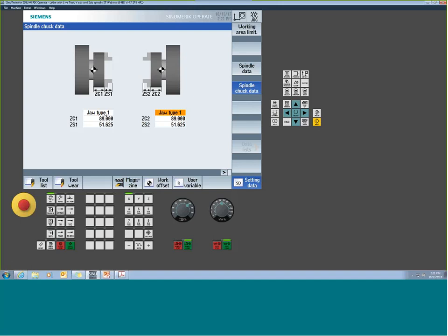Now, if it's a case where it's like a collet and the body to the base collet position is the same value, you don't have to have a number in here for the jaw projection. You could set it to 0. You just got to make sure that it knows where the front of that thing is, because the next step is going to be us telling it how far out the part sits, and that's going to be relative to this jaw face.